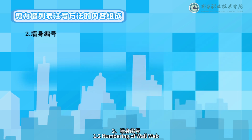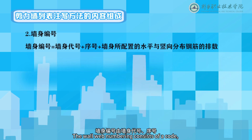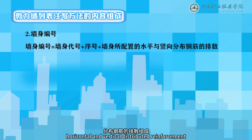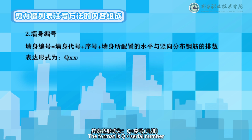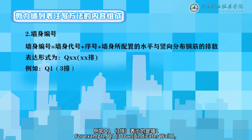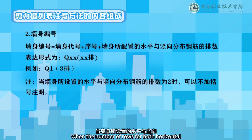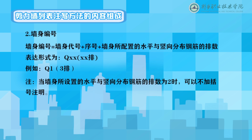1.2 Numbering of wall web. The wall web numbering consists of a code, a serial number, and the number of rows of horizontal and vertical distributed reinforcement, with the number of rows shown in parentheses. The format is Q plus serial number, number of rows. For example, Q1, 3 rows, indicates wall 1, with 3 rows of both horizontal and vertical distributed reinforcement. It should be noted that when the number of rows for both horizontal and vertical distributed reinforcement is 2, it is not necessary to indicate it in parentheses.